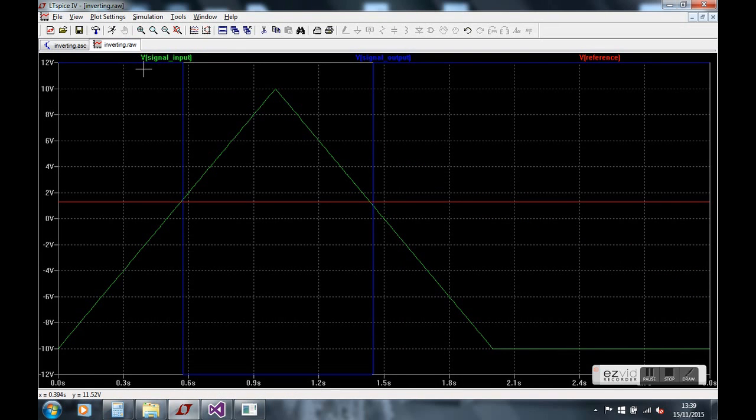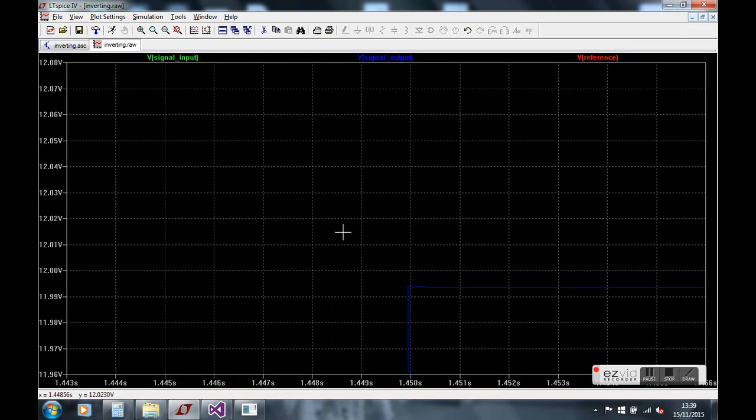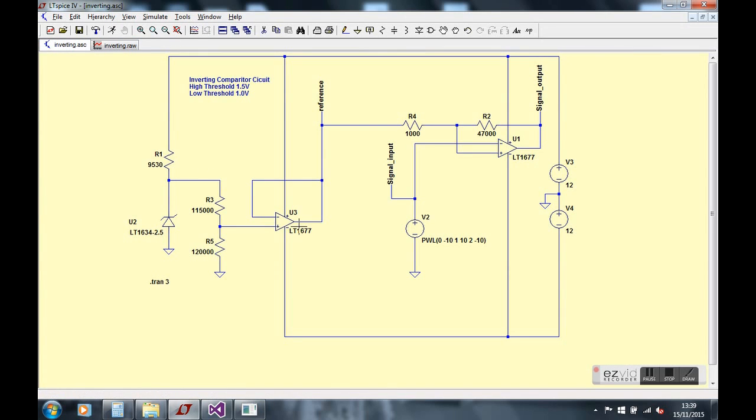The component values that the tool suggested were exactly right. There could be a little bit of error because the comparator that's providing the positive feedback isn't at the 12 volts, which you can see here. So this is the high output of the voltage comparator, and it's 11.993 volts. So that's the reason why there is a millivolt of error. Okay, so there you go. This is a circuit that's required for precision switching thresholds.